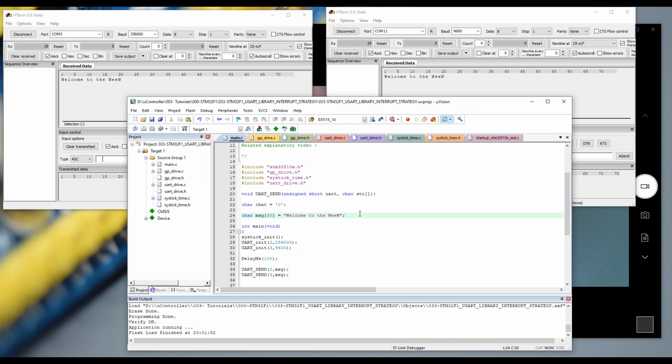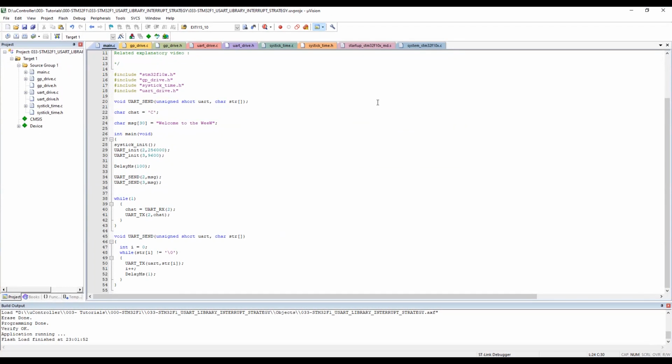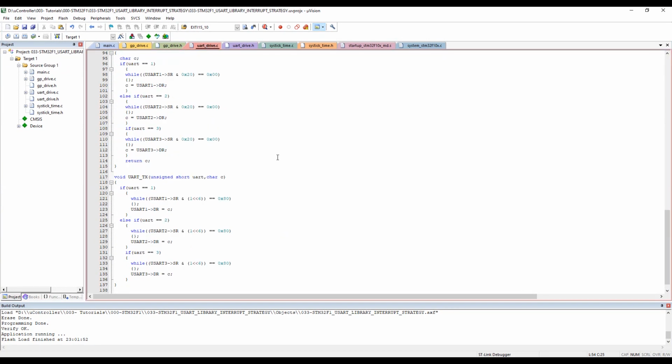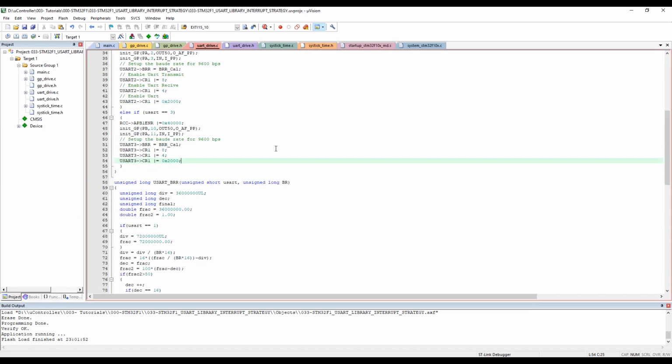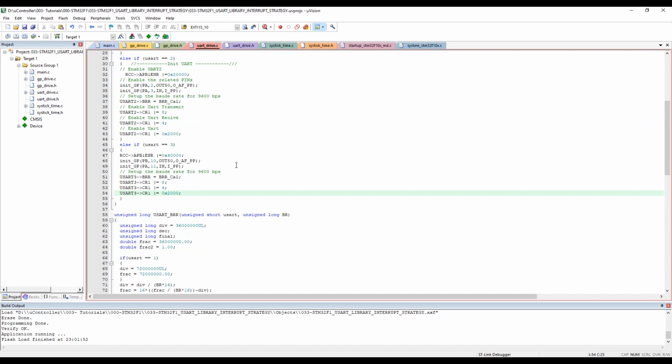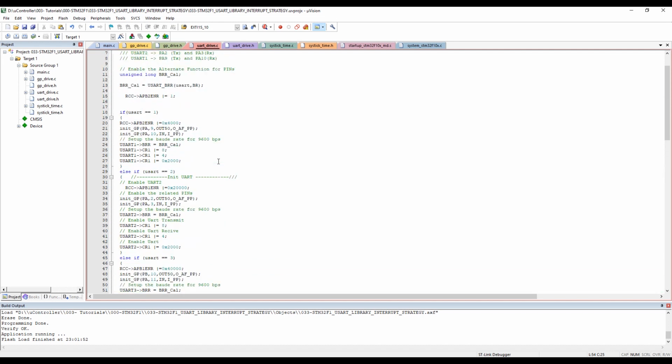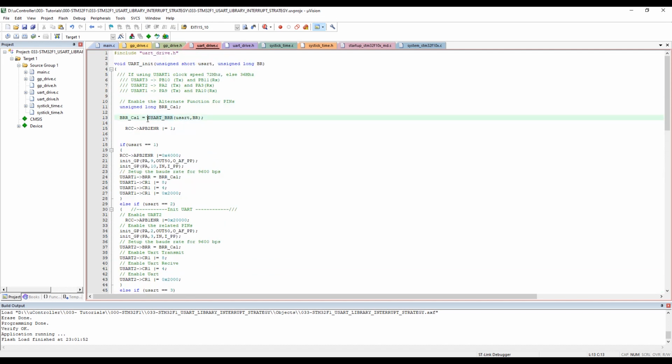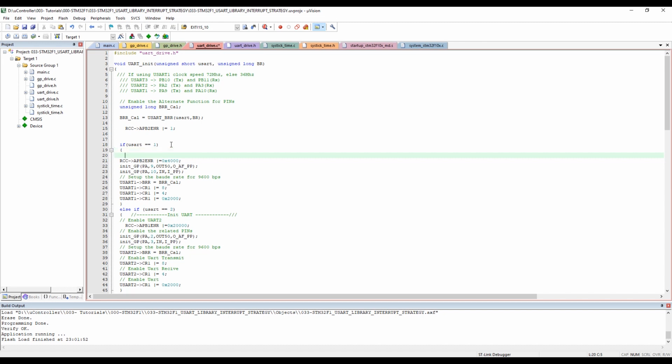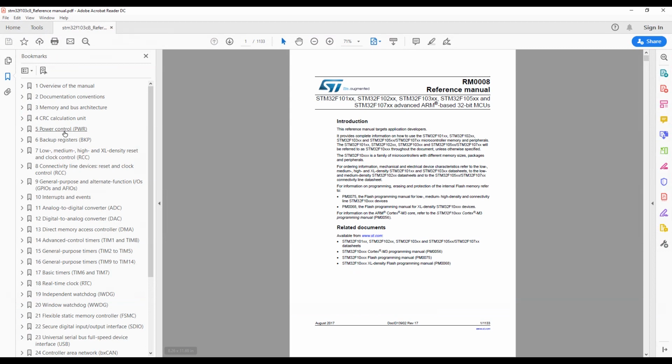For the next step, let's start putting in the interrupt routine. So we go to the UART library, and the interrupt setup will be inside the initialization, which is exactly here. So inside the init, we start here. We will be repeating the same thing each time. It will be disable IRQ before starting all the setup. And I need to open and check here.